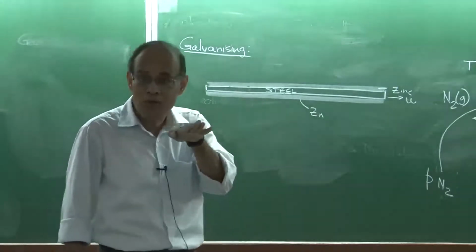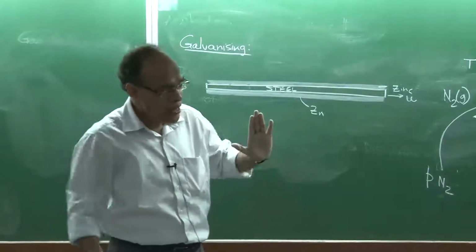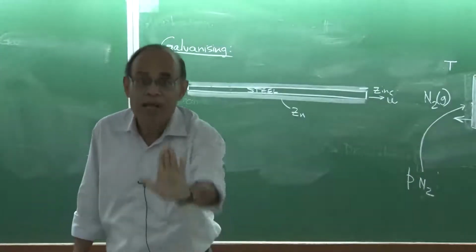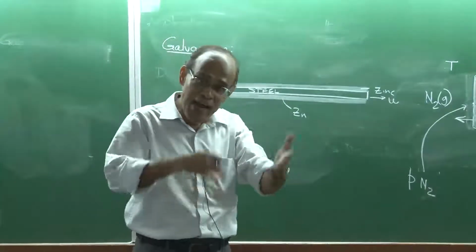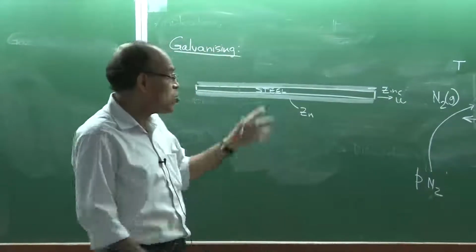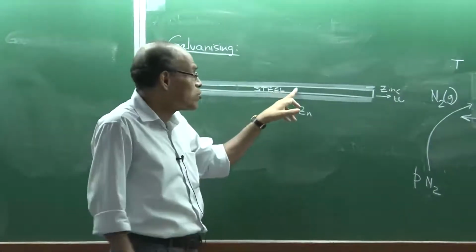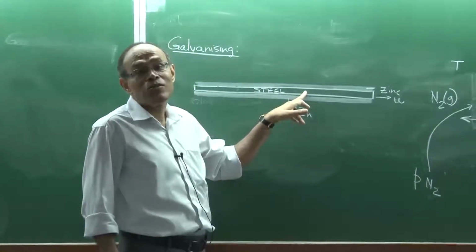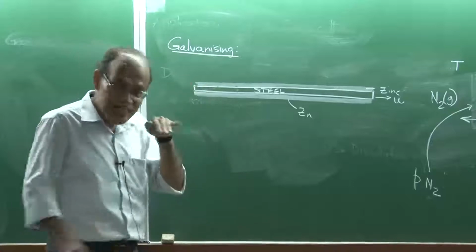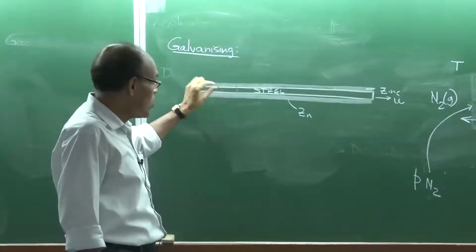There is a fluid flow part involved in the whole thing, because the plate will come, and there is a huge bath in which molten zinc is kept. The hot rolled coil comes, enters the zinc bath, travels, and after some time goes out of the bath. So there is fluid dynamics involved. Because of the movement of the plate, there is some stirring in the system. Then there is solidification involved because of temperature, and then the liquid zinc itself starts to diffuse into the solid steel. That is also another aspect of it. So this bonding part particularly, okay, where zinc diffuses into the iron body and forms certain intermetallic compounds because of chemical reactions, is of interest.